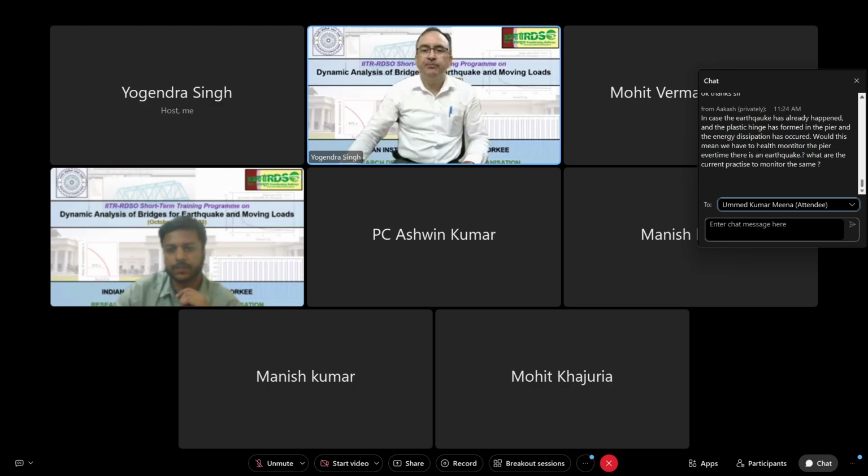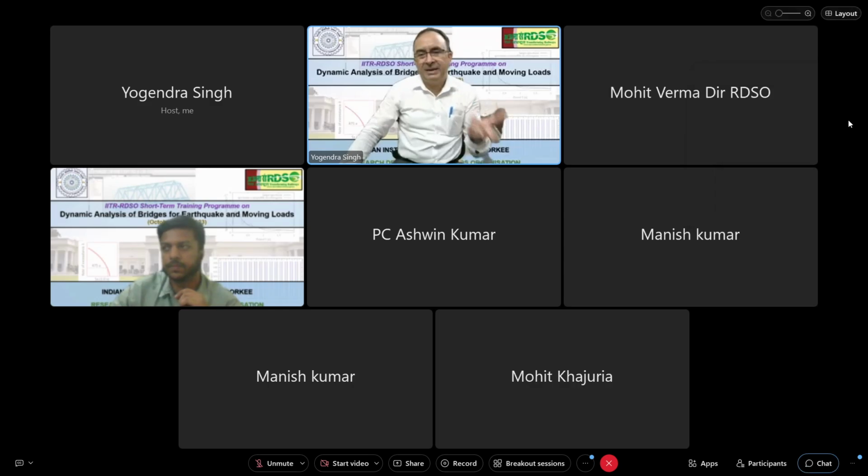Some of the people say, when I was talking about pile foundation, pile is also like a column, and we can design those piles also to develop hinges. But the problem is inspection only, that it will be very difficult to inspect the piles after the earthquake, what has happened there. So that's why we limit our plastification or plastic hinge formation or the damage to the base of the pier, sorry, and that we can inspect.